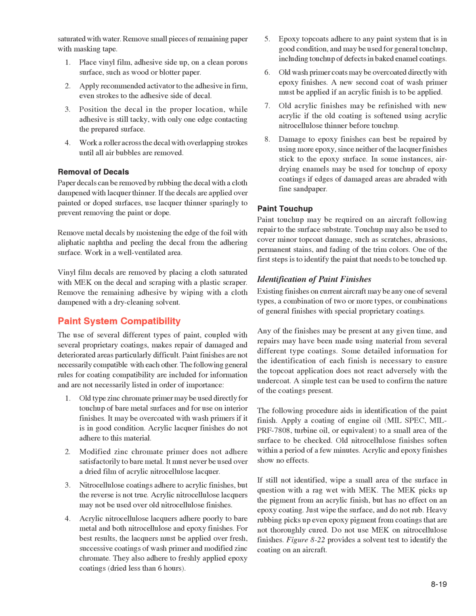The use of several different types of paint, coupled with several proprietary coatings, makes repair of damaged and deteriorated areas particularly difficult. Paint finishes are not necessarily compatible with each other. The following general rules for coating compatibility are included for information, and are not necessarily listed in order of importance. 1. Old type zinc chromate primer may be used directly for touch-up of bare metal surfaces and for use on